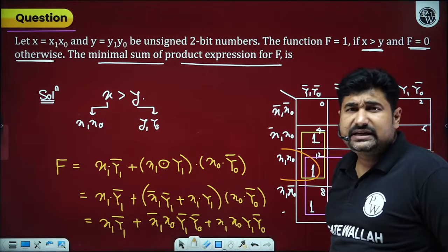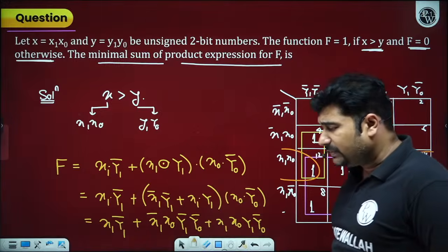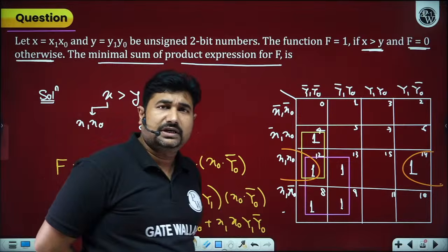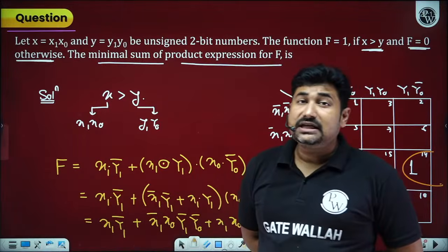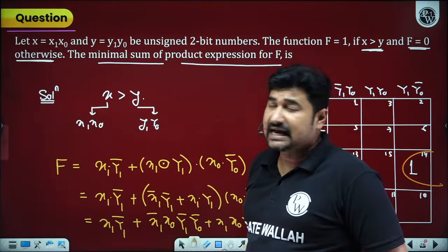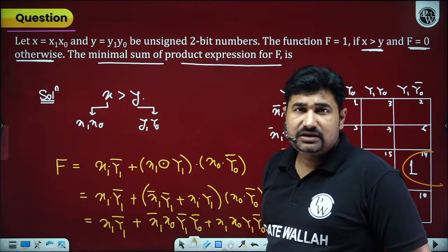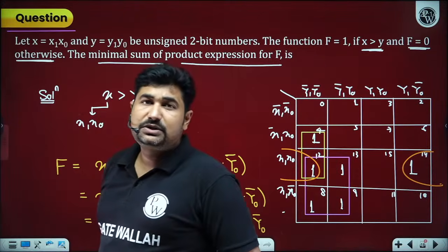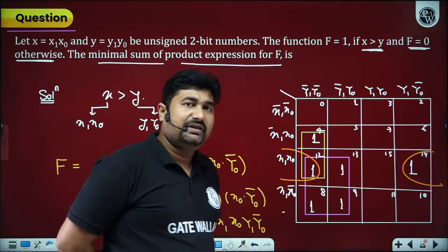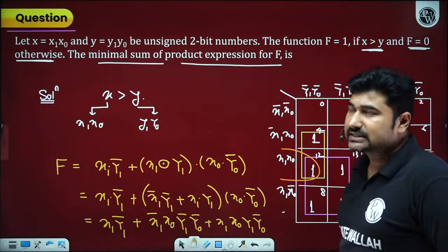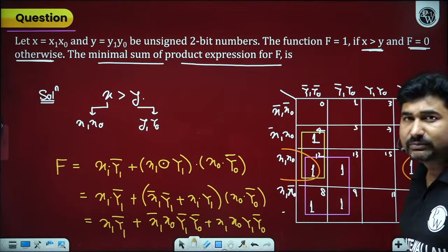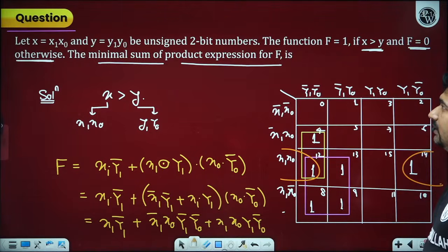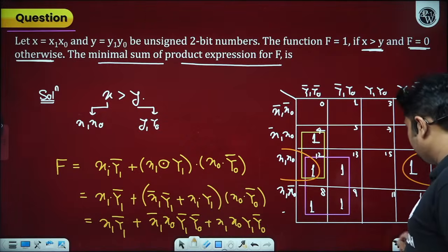How to design any desired combinational circuit? First, we need to understand the input-output relationship, construct the truth table, write the logical expression, minimize it, and implement the logic circuit. I am doing the same thing. We have learned comparator so far. A comparator is used to compare two binary numbers. They may have an equal number of bits or an unequal number of bits. How many of you are able to understand up to this part? Is it okay? Great, sir.